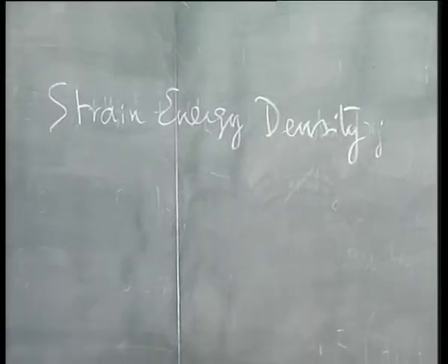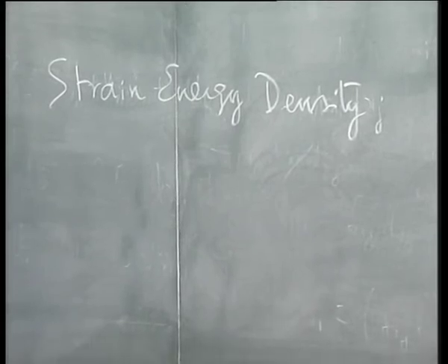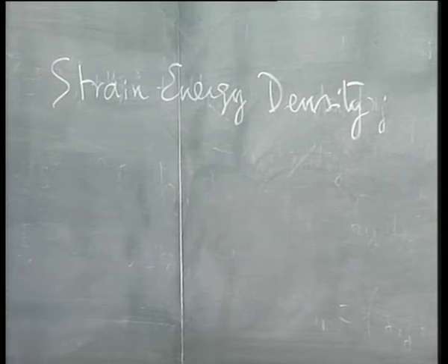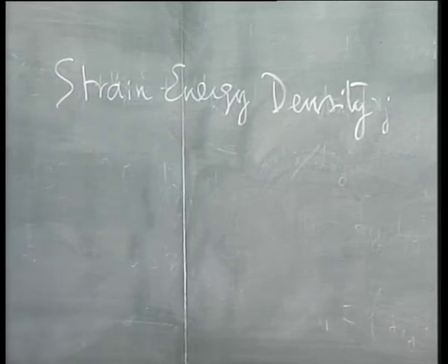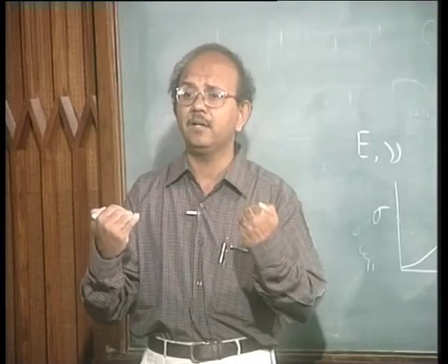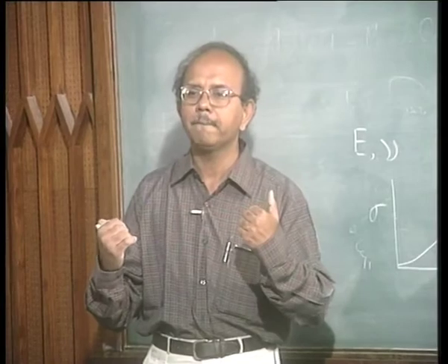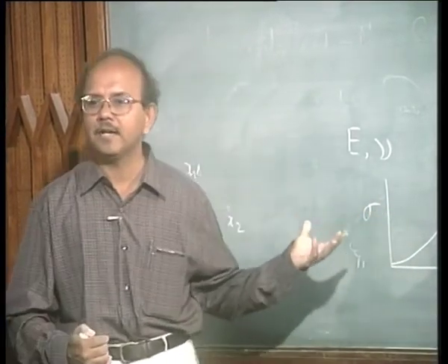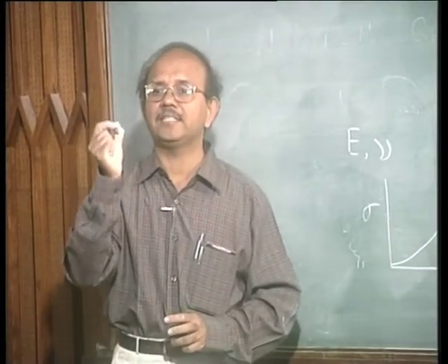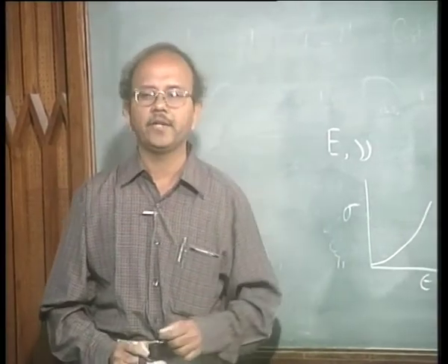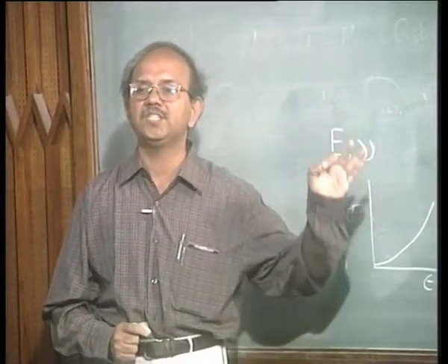Again, I am sure strain energy is not a very new term. You would have gone the other way. From the stress strain curve, you would have said that strain energy is nothing but the area under the curve. Okay? That is a nice way of looking at it in your earlier classes, but you would find that at this level strain energy is much more fundamental than what we call the area under the curve. In other words, we are going to define the elastic material itself from strain energy or strain energy density function.